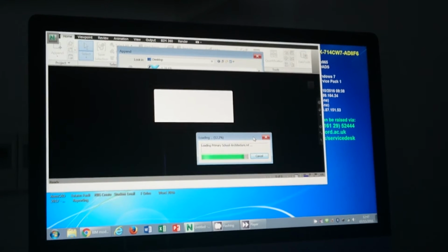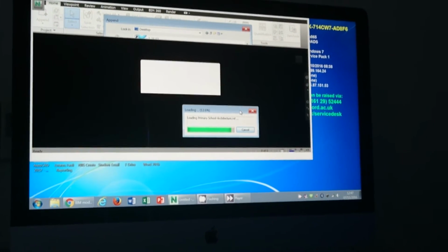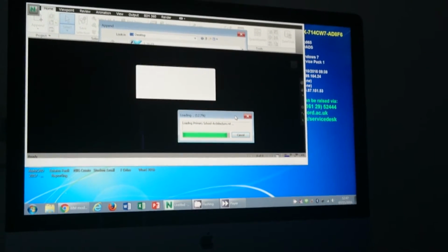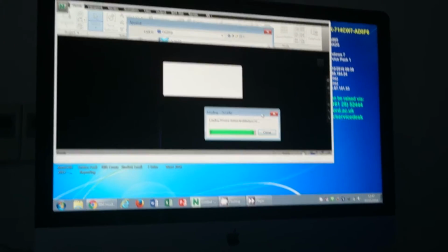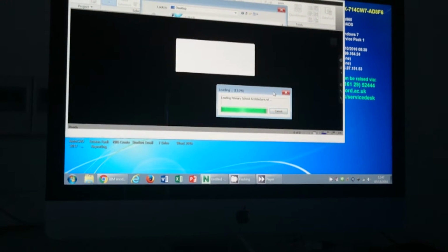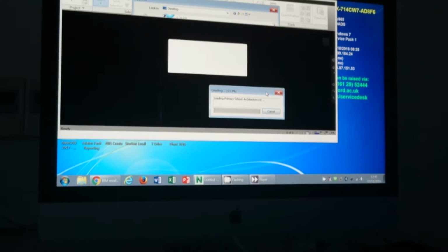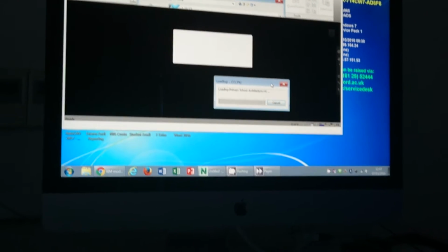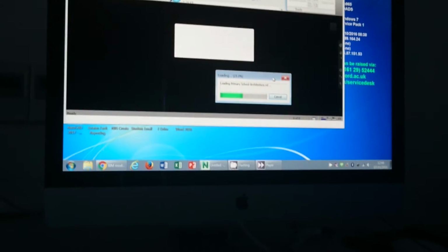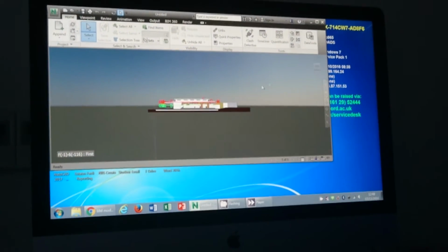So you went to open a project directly, just Revit? No, I just clicked append. From the first ribbon you've got append. Here you have append and merge. Append is simply open, merge is open and get. You just append the architecture one. If you have more than one, do you click all three together at the same time? You can. Append and then choose the structure, mechanical. So we opened the file.